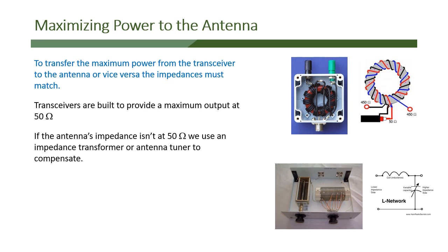And again, if you're using a handy talkie primarily, it's not going to have perfect power transfer because it's a very inefficient antenna. But there are ways to deal with that: you can use an external antenna, which is designed better than a handy talkie antenna.